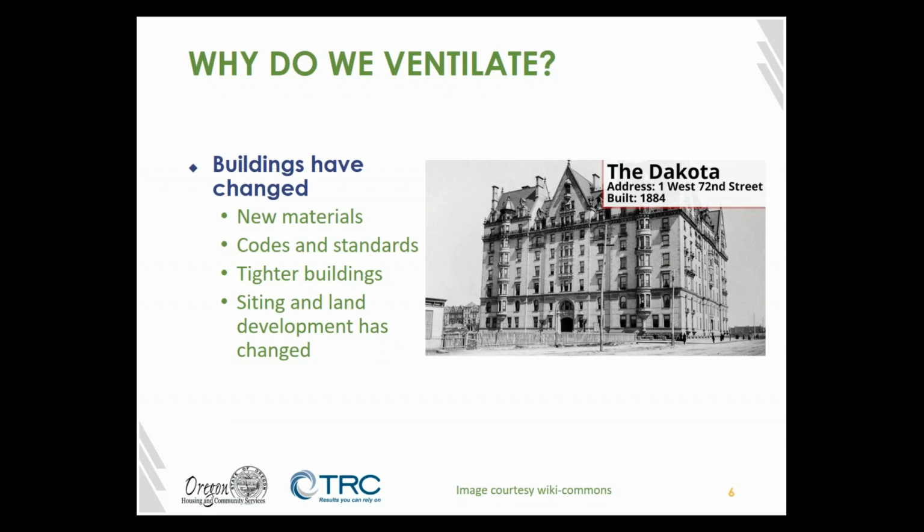We have these chemicals, we have radon, we have all these things being introduced to our indoor environment that probably weren't there before at as high levels. We also have codes and standards pushing for health and energy, regulating and mandating the need to regulate indoor air quality for the health of our occupants. We also have tighter buildings, which means they're not moving air in and out naturally as much as they did. Natural ventilation isn't as easily achieved.